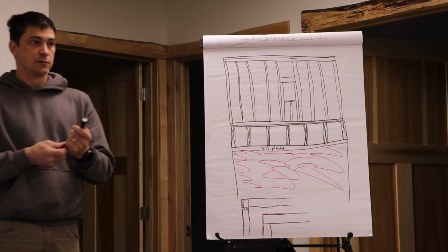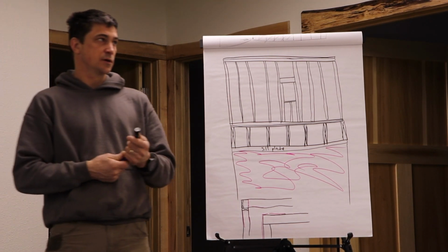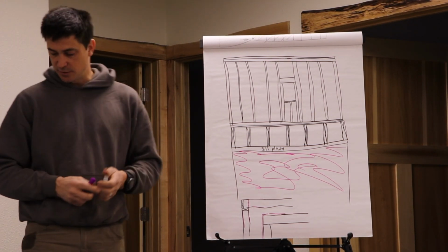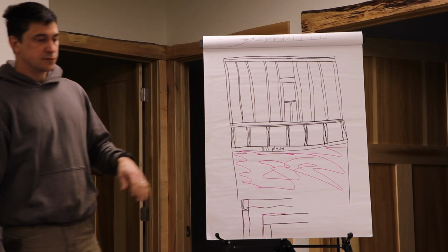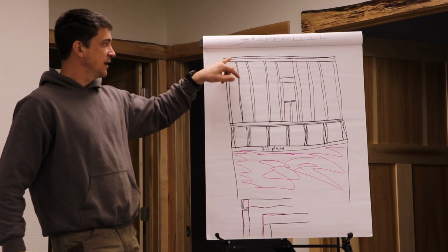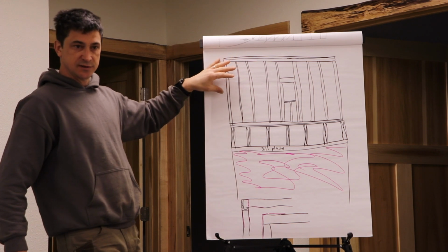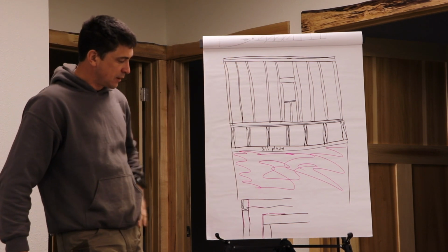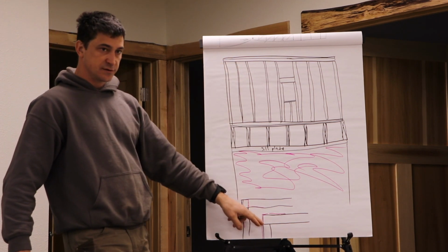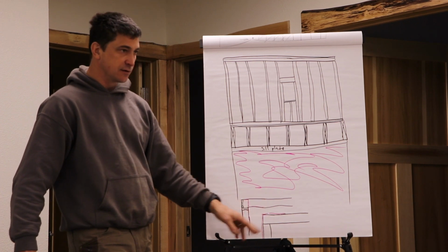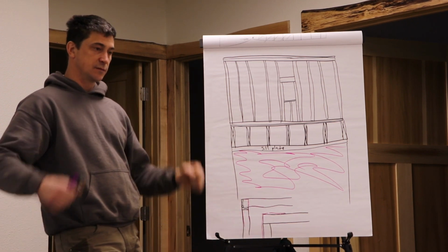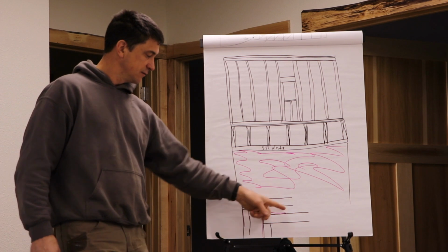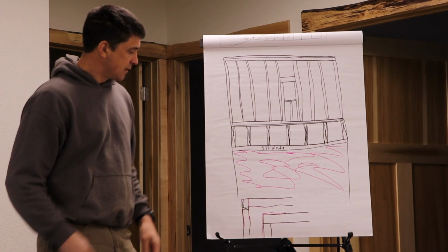Do we do that on this place at all, or no? I think these all have double top plates here. So we don't have to have the double top plate. We can build with a single top plate. But when we do the single, we have to tie it together, and that's why we'd have to have that metal strap along the outside.